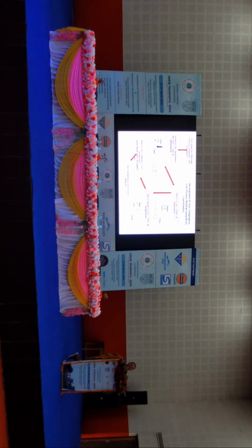So the next one is the Kamal and Sourour cure kinetics model. Have you heard of the Kamal and Sourour model earlier, which is called the autocatalytic model? So what is an autocatalytic model? It doesn't need any extra catalyst; the reaction itself catalyzes itself through the increase in temperature due to heat evolution. So you will get the rate of cure as a function of time at different isothermal temperatures. From that you can model the cure kinetics. So you will get d alpha by dt as a function of alpha and t. d alpha by dt is the rate of cure, a function of the degree of cure and the isothermal temperature.